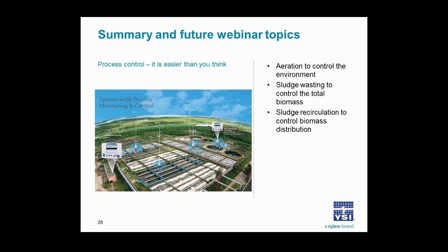Yeah, I was waiting for somebody to ask that question. Really, it's a matter of controlling the sludge quality. Again, this can get into the philosophical range as well. But here's my understanding, and you may disagree or comment. The sludge quality is really what affects the settleability of the sludge.